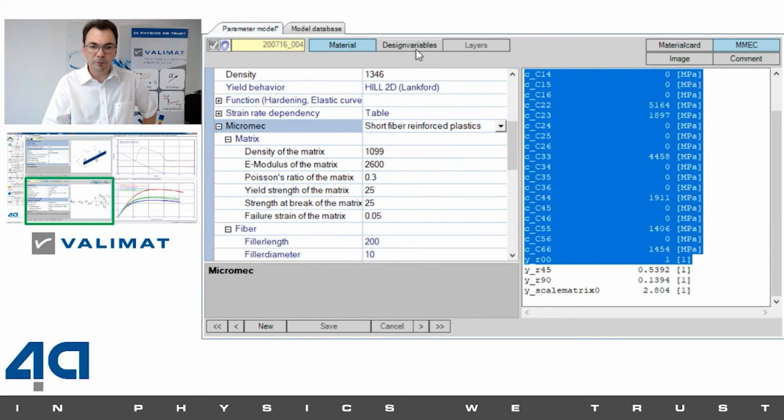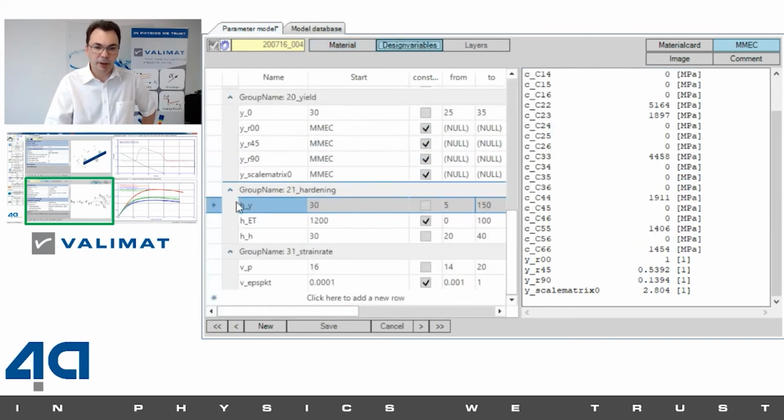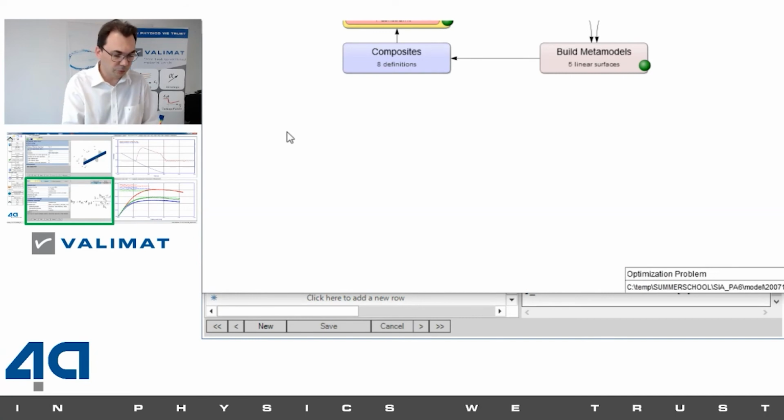And now we have to fit the hardening function, and therefore we can do this for this MAT 157 too, same as for MAT 215. We just have to fit the viscoplasticity values, the VB factor, and the hardening function. And if we look then, I already did this optimization. So I will open LS-DYNA to show you what happened in the background.